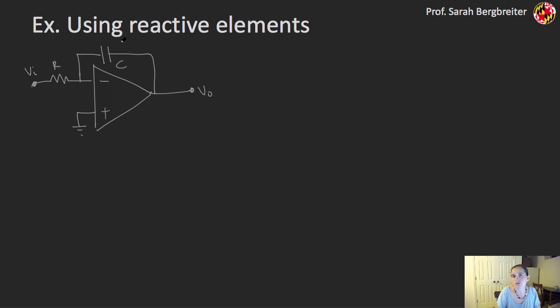And the short answer as to how we're going to do this is exactly the same way, but instead of thinking of resistances, I'm going to think of impedances. A capacitor or inductor would just show up as a complex impedance. So the impedance of this term right here is going to be 1 over j omega C. At high frequencies, this looks like a short. At DC, it's blocking current. I'm going to analyze that the exact same way.